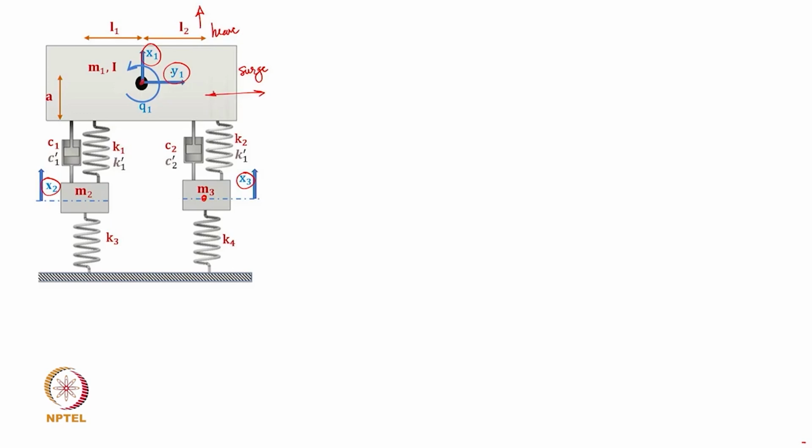So, this is another degree of freedom that we are including. Now, these two, and with theta as the additional pitch degree of freedom for the chassis mass, these three are the 3 degrees of freedom for the chassis, and then 2 more degrees of freedom for the wheels. That basically suffices to capture the dynamics of this particular system.